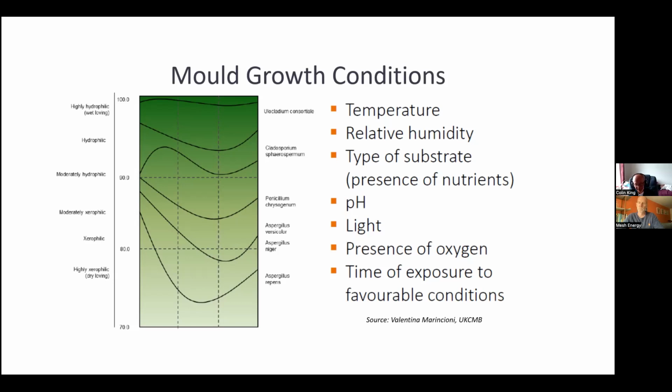Because what you don't want to do is leave any weak spots. The main issue with the brick creams, especially with the work that I've done on Storm Dry, and I did a lot of testing on some of the snake oil versions of these materials, I did a report with UCL on the efficacy of brick creams and wall treatments, which I'll send you the link to. Government actually published it, and we did a lot of laboratory testing on how it affects the porosity, does it allow the building to still breathe, does it do what it says on the tin? And to be honest, the only one that came out close to what they claimed was the Storm Dry system.